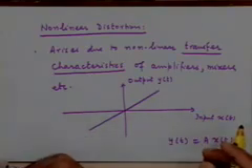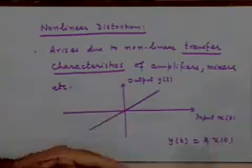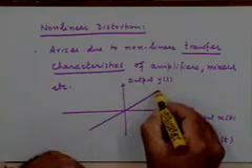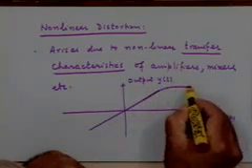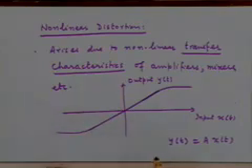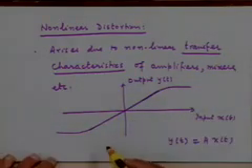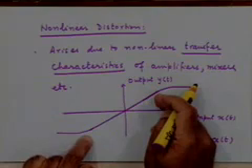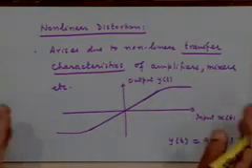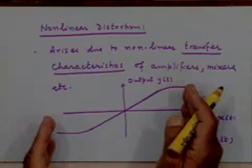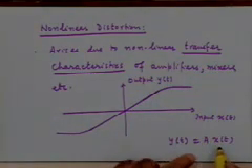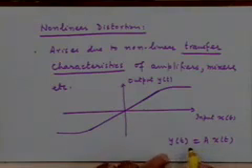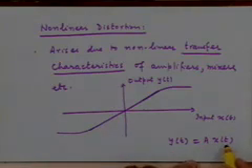the saturation nonlinearity, right? You know the effect. It basically arises because you have some finite values of the power supplies, and because of this, as your input signal becomes larger and larger in amplitude, instead of being linear like this, you get into this nonlinear or saturation mode like this. It doesn't remain linear for all values of the input amplitudes. So as long as your input signal is within the linear range, you are fine. But if your input signal goes beyond the linear range, then the output is no longer proportional to the input. Y of t is no longer A times x of t, and that is a nonlinearity.